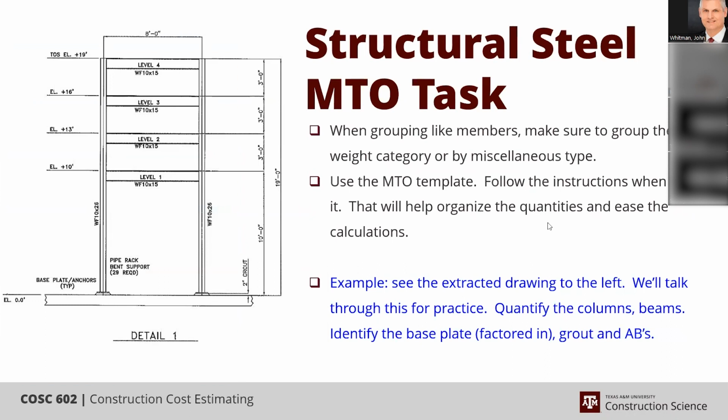So this is a typical cross section, a little bit simplified. In fact, this one here looks just like what you will be dealing with. In this case, remember that even though the flange ends right here, the webbing is still here, and so this beam is going to reach all the way over to the center line. So you want to take the full length of the center line on these items.